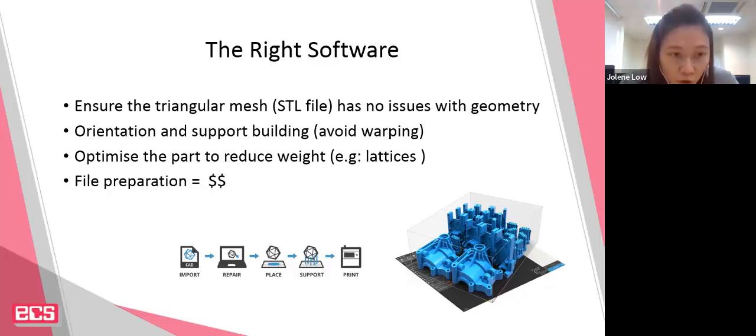The last point, 3D printing software now can even do certain optimization of parts or modify certain parts for additive manufacturing purposes, like lattices or even splitting large parts into multiple small pieces so you can do printing in the restricted build volume.